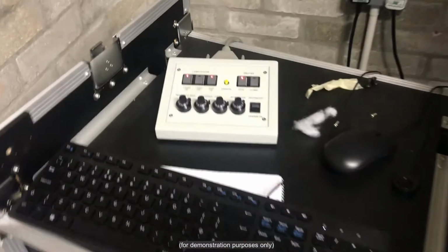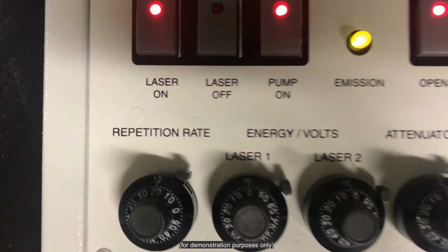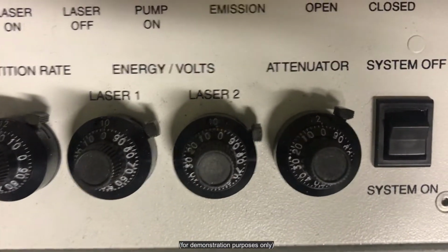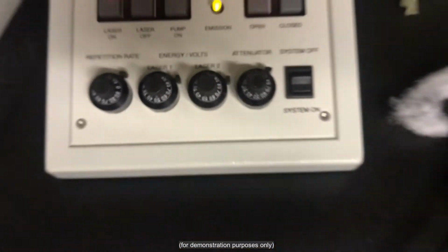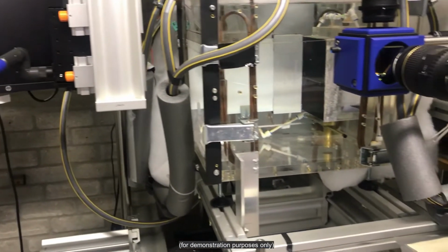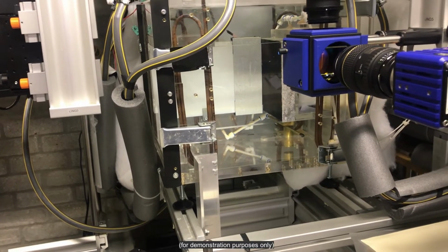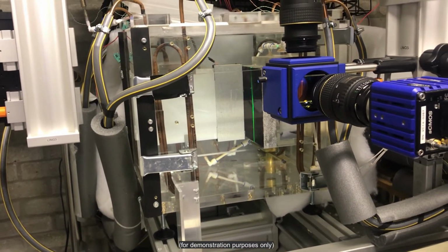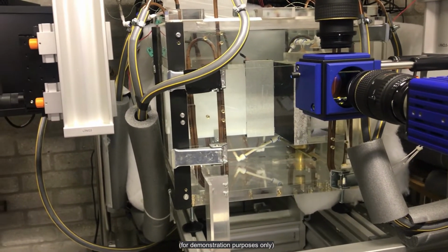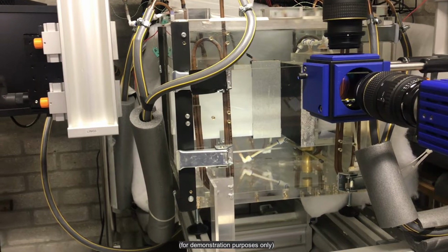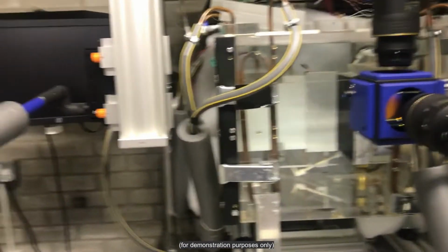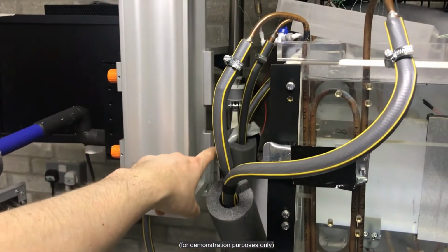Just doing this alignment, the power of the lasers themselves is actually quite high, that's full power, and using the attenuator, about 20% of the full power is being allowed through. You would normally start at 10, 20%, up to 30% whilst aligning the laser, as it provides enough light that you can see it, but is less of a hazard to yourself, both from reflections and from direct strikes from the laser beam.